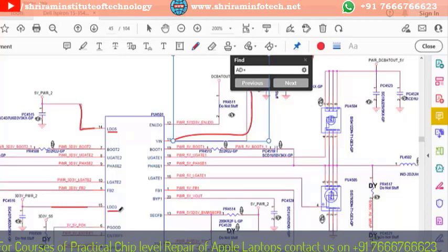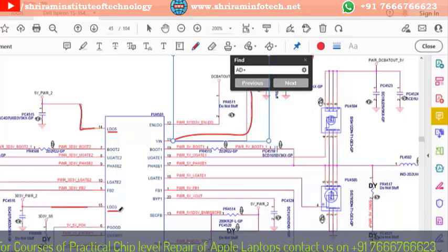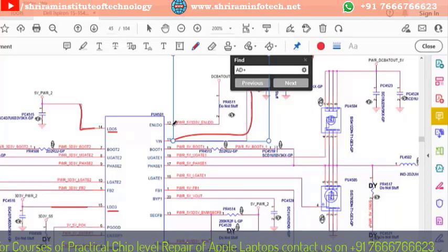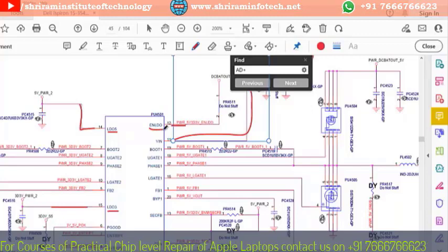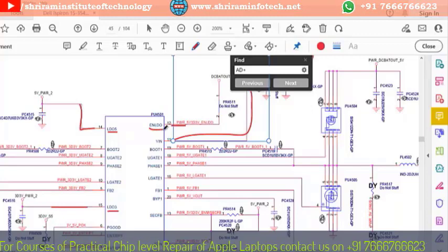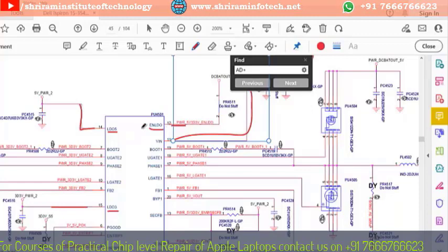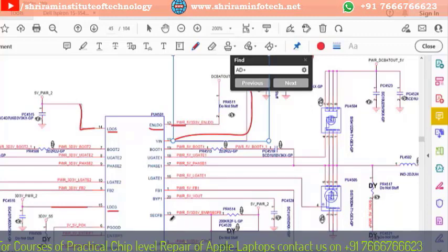You can see our another video, where everything is mentioned in a very animated way. So here you have to check the voltage. If the voltage is not coming here, then you have to check this point, pin number 12. This is called the enable LDO. There are 2 enable signals, one for the linear enable and another for the buck enable.